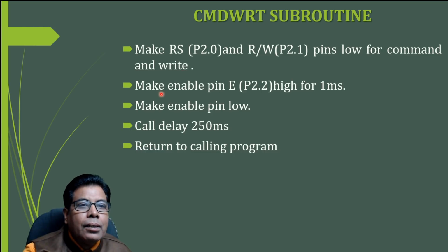Then make the enable pin E, that is connected to port 2.2 of 8051, high for 1 millisecond. Then make it low. This 1 millisecond is the time when the pin will remain high and the writing of the command will be completed during this 1 millisecond, as we have seen in the timing diagram.